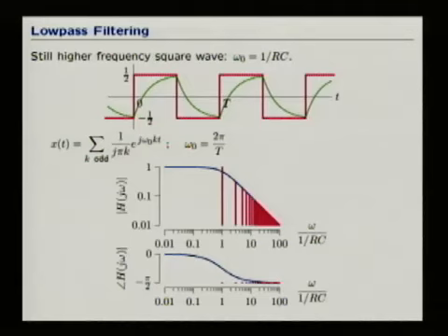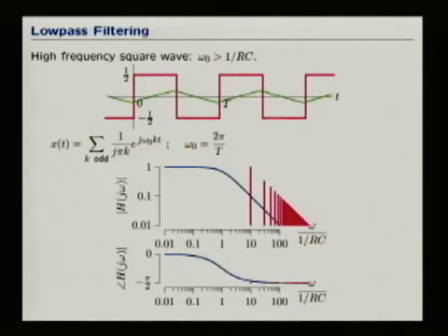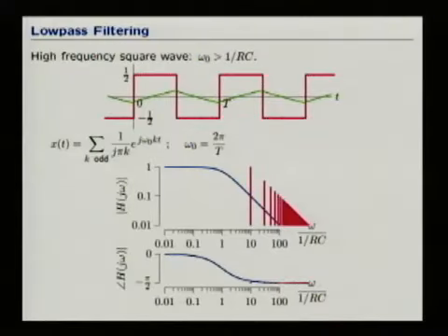If they all pass through the low-frequency part of the filter, so that the gain is 1 and the phase is 0, the output looks just like the input. And if they all pass through the part of the filter that's sloping down with a slope of -1, with a phase lagging by pi over 2, you turn a square wave into a triangle wave. That was the simplest example of a filter.